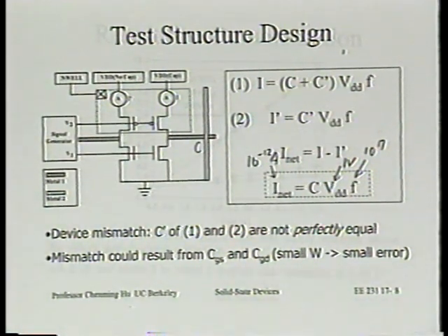First of all, the ammeter is not called on to measure the charge in 1 cycle. The ammeter is integrating over a period of time. That's how it gets sensitivity, all right? And so over that period of time, you're not talking about 1 electron anymore. That's why you get this picoampere sensitivity of 0.1 picoampere. Certainly within the sensitivity of the ammeter, no question about it, all right?